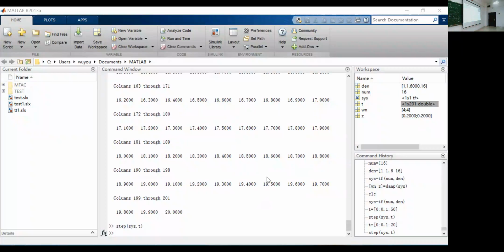How to do it? Let's see here. Let's see characteristics, peak response. If you choose this, a point appears here, and it says the system name is sys, which you just defined, right? The peak amplitude is 1.53, and overshoot is 52.7%. And at which time?